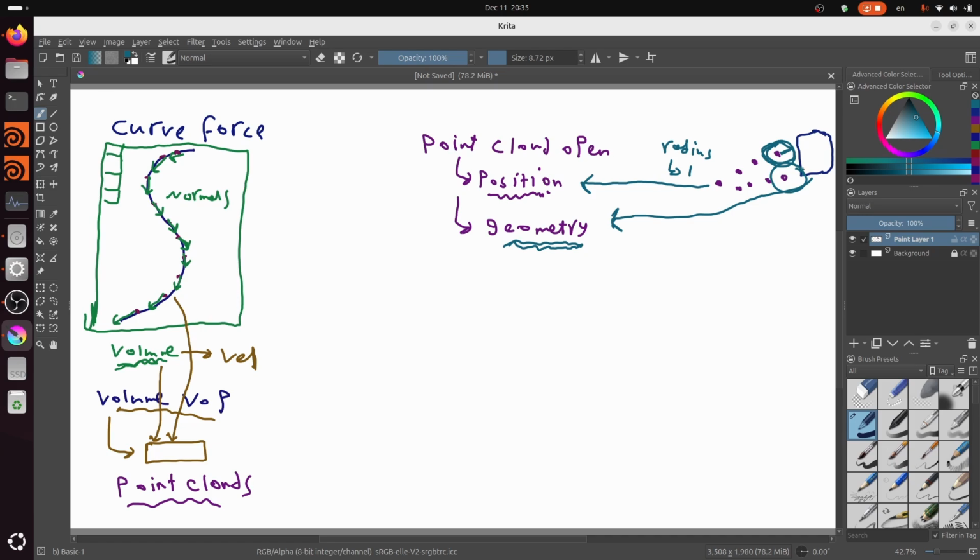So for example, if this particle here, let me select this particle, if we are searching here in a radius like this, and this radius finds this point here of this geometry, or it may find 3 or 4 or 10 points, you can set the maximum number of points that it finds.